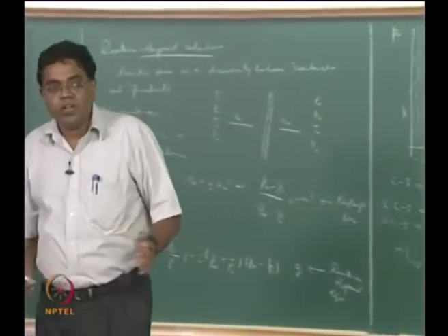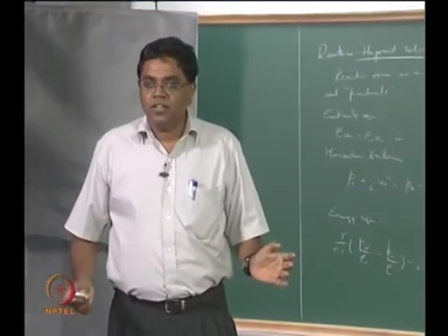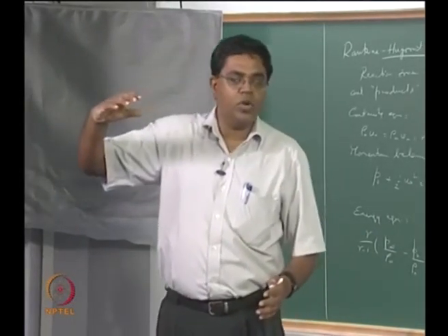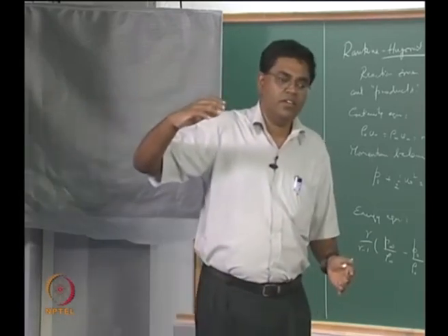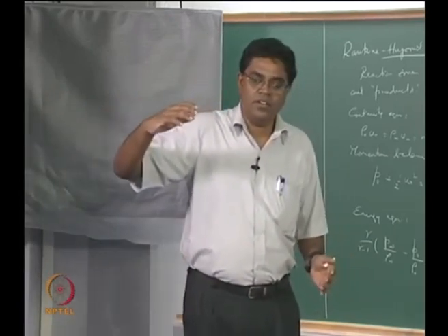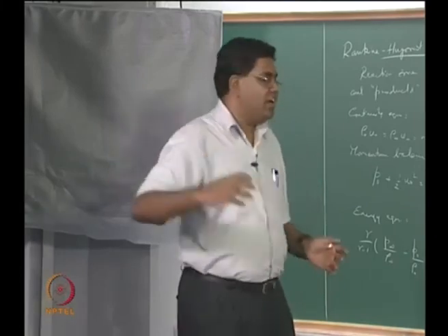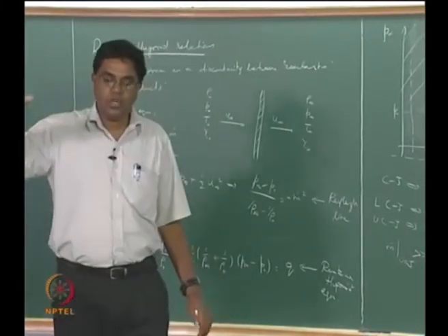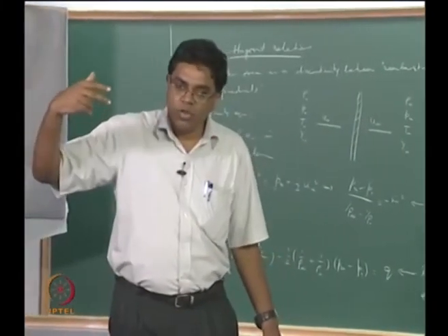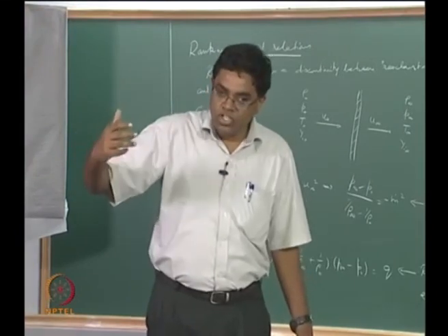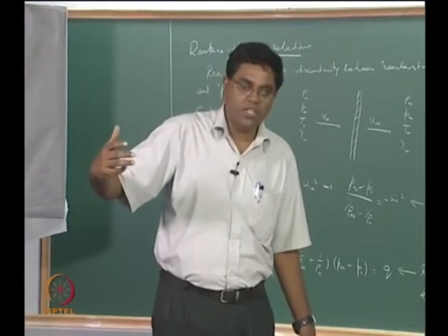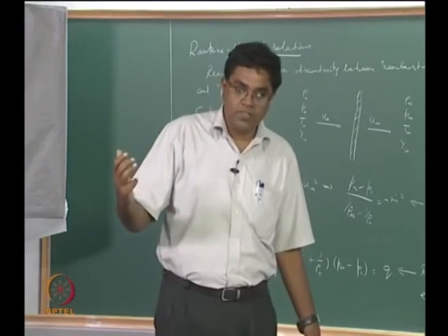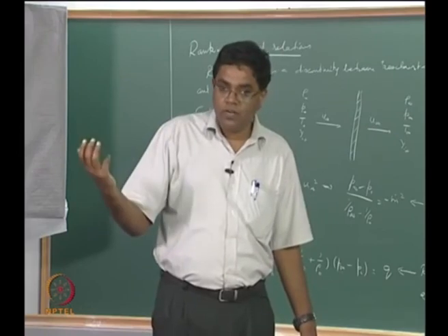The answer is we don't come across that at all, right? So in Bunsen burners and stuff you don't really get supersonic flows. So what's going on? The answer there is outside the picture of what we are talking about. We started out with the mass conservation equation, and then we went through the momentum conservation, and then we went through the energy conservation. We also talked about the species conservation, but the energy conservation, keep in mind, is essentially coming out of the first law of thermodynamics, but we never really considered the second law.